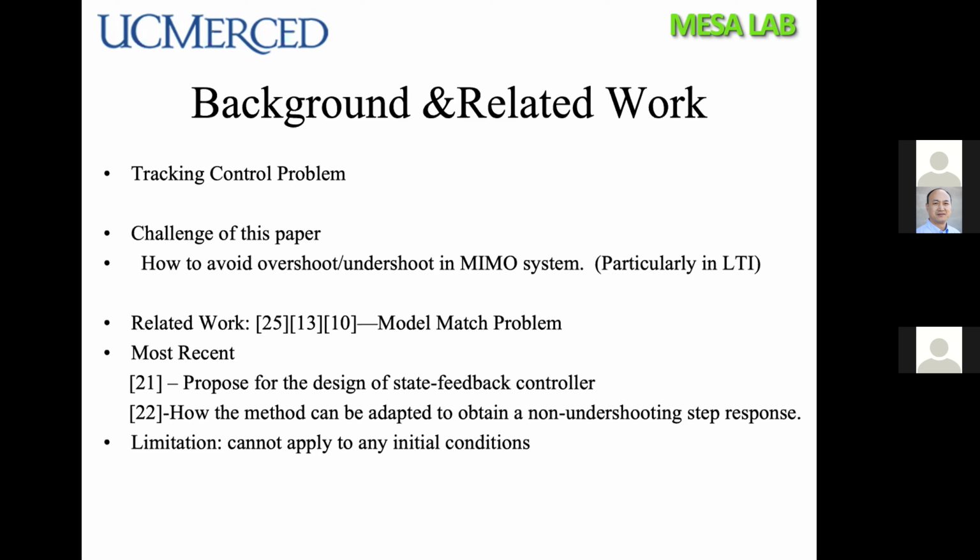A recent contribution offering a design method for MIMO systems is reference 21. This paper proposed the design of a state feedback controller to yield a non-overshooting step response for LTI MIMO systems. Importantly, this design method is applicable to non-minimum phase systems. It doesn't assume that the system state is initially at rest and can be applied to both continuous time and discrete time systems.